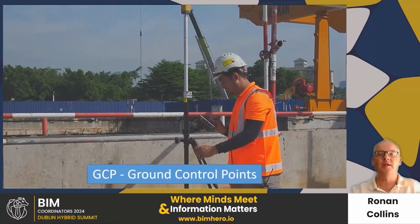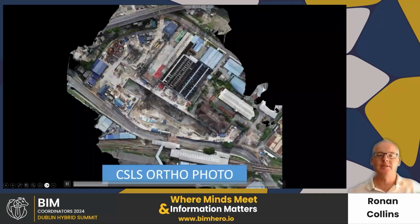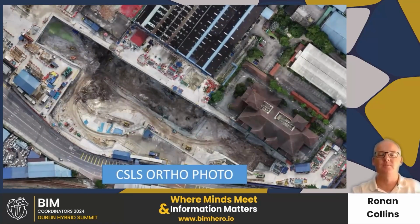And by incorporating the ground control points, once you've created the reality mesh, you can then link that back into the BIM environment very quickly and very accurately. So a couple of things come out of this process. The first one is orthographic photographs. This is a way of creating a true orthographic image. This can be used in GIS, and in CAD solutions if you're still using CAD.